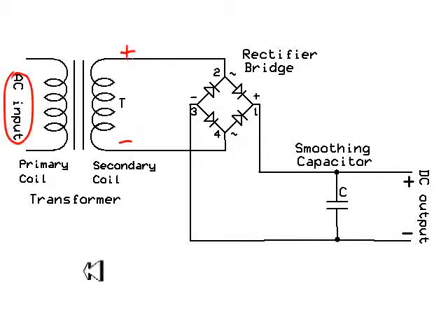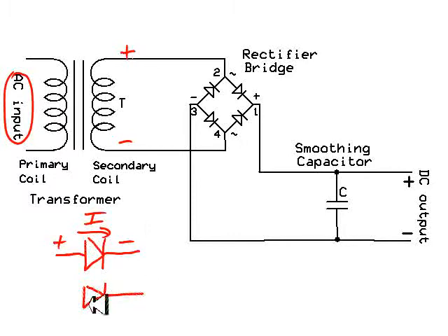Remember that a diode, and here's the symbol for a diode, allows current to only flow in one direction. So that's the flow of the current. If this end is positive and that end is negative, current will flow. But if you try to make this end positive and that end negative, you will get no current. So, coming back up here to our transformer, the output is AC.